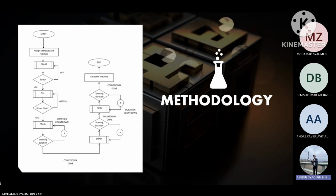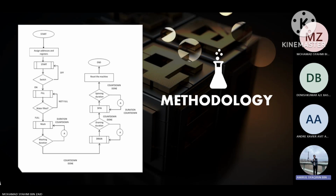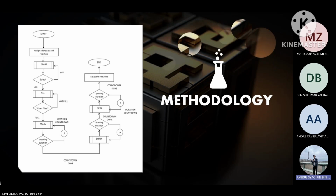The fourth step is we set how many times the program restarts from the beginning to get 3 washing cycles. The fifth step is we start the subroutine with the duration for washing, draining, and spinning, and then the status of the switch is checked. If the switch is on, the software will go to the fill subroutine to fill the tank. It will start by washing, draining, spinning, and then follow the steps as we assigned them in the coding. The next step is the fill subroutine.